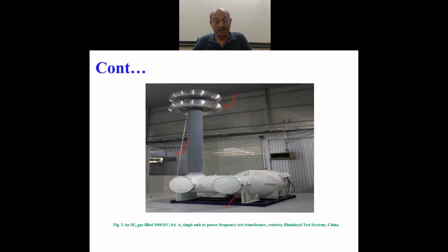Inside the bushing, there would be SF6 gas or oil insulation, but in the air, 1000 kV, if you do not extend the size of the electrode, there may be very strong partial breakdown phenomenon there, which is controlled by stress control method we have talked about, by providing very large size of the electrode wherefrom you get the high test voltage.